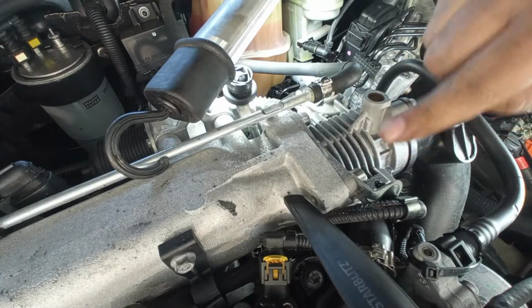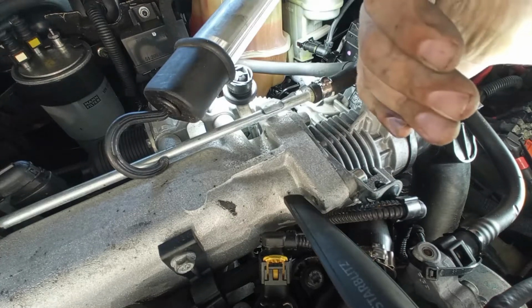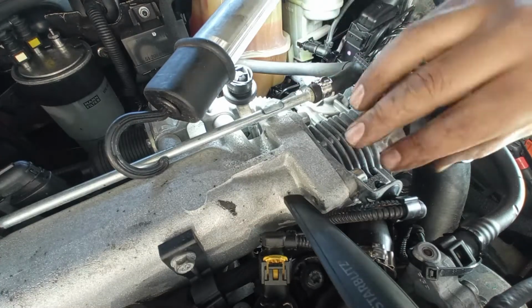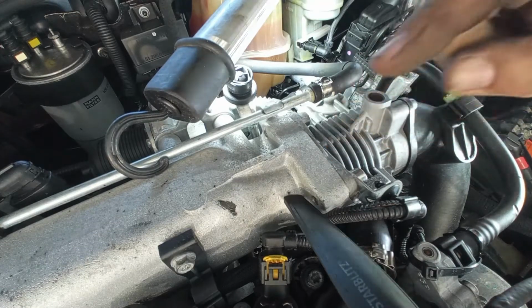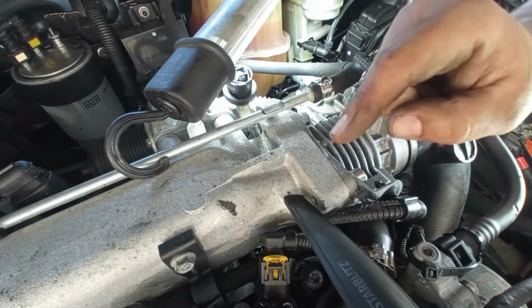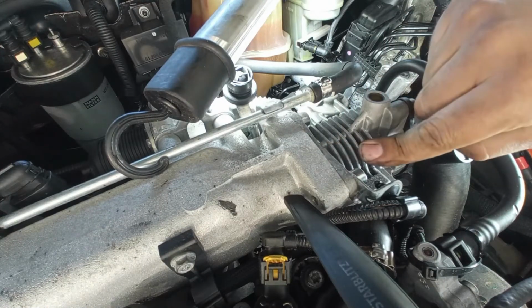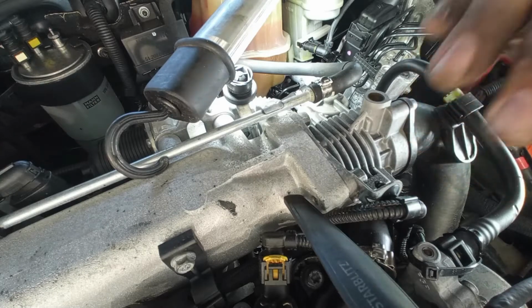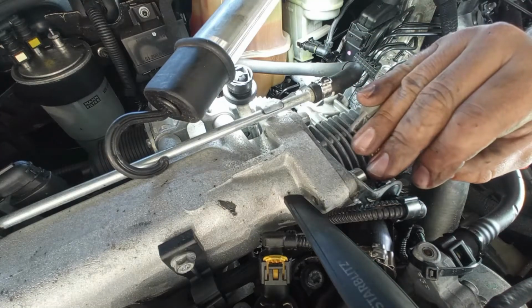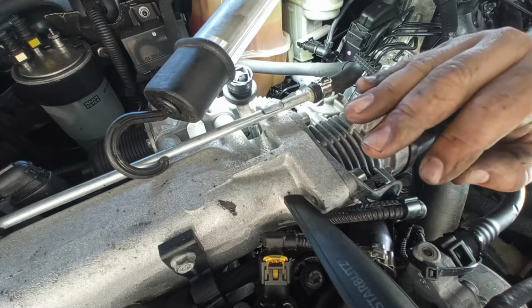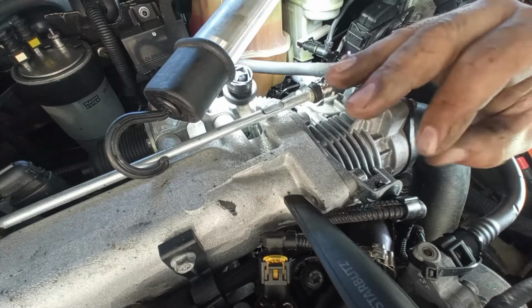This intake valve, this throttle valve is gone, okay? In that way, if you cannot regulate the EGR or help to regulate the EGR with this throttle valve, you will not have correct regenerations. Again, the DPF cannot work correctly. This is another problem. This problem here is present because of the massive oil leaks that were present on this engine. I believe everything that is happening on this car in terms of failure of DPF, it is because of lack of maintenance.